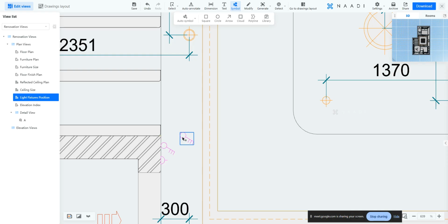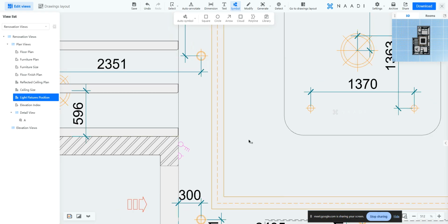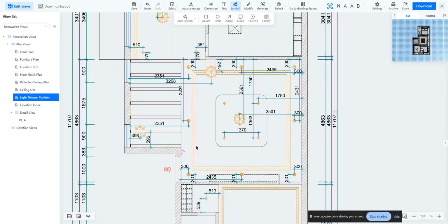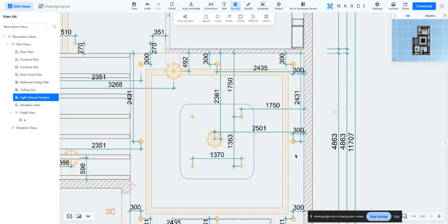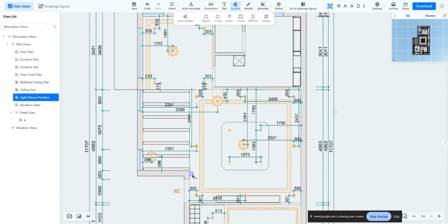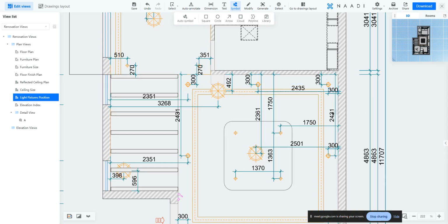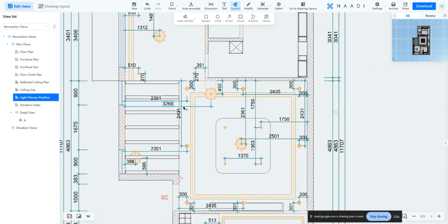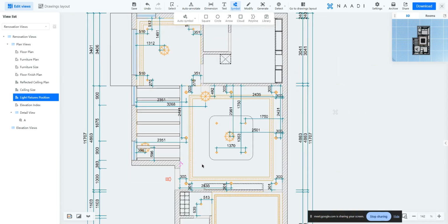So if you want to use some reference line to place a component or so, for now, you can use this polyline as a reference line. But we are working on systems to actually add a reference line which will help you in your electrical drawing process too. But yes, your electrical drawings can be created here in this process. The symbols need to be manually added, but in your plan, all your electrical points, everything in your ceiling and everything will be automatically notified. Your electrical symbols beyond that can be added here manually.